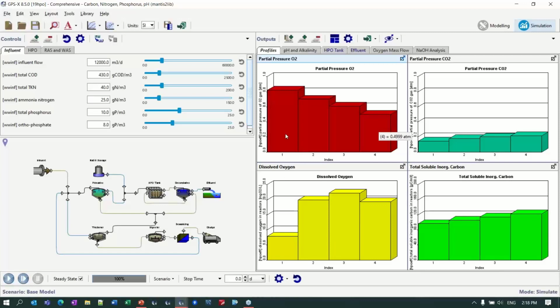The balance of the oxygen transfer and all that biological activity is giving us the following dissolved oxygen concentrations here. I wanted to plot this to make sure you see that this is like 8 and then 19 and then 22 and so on. Of course, this is what you see in an HPO system because of that very high saturation concentration. It allows you to have DOs of above 10, where the normal limit that you would see with air. Here we can get up into the 20s as well.